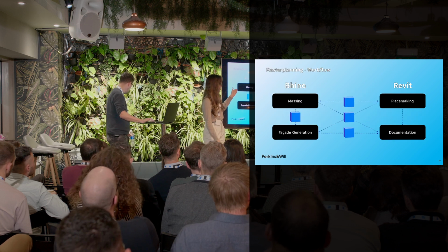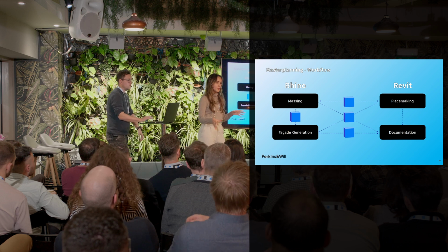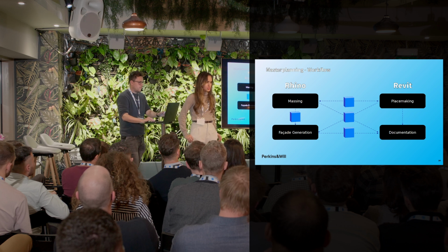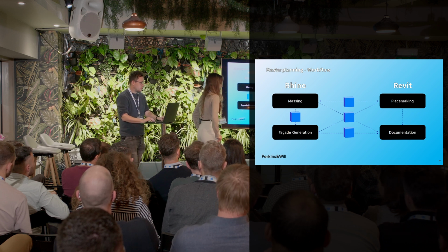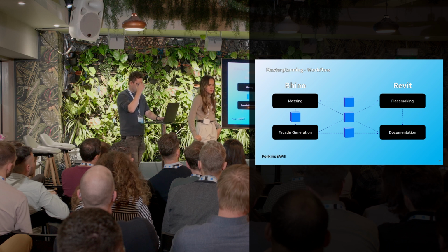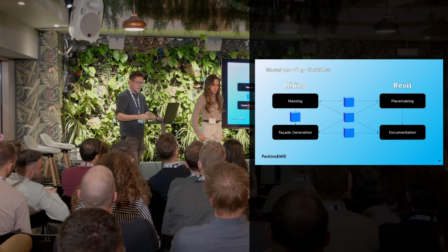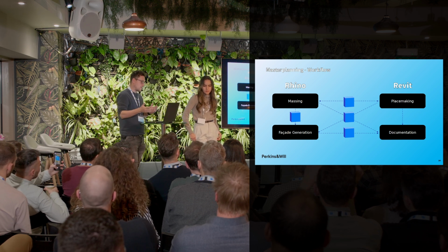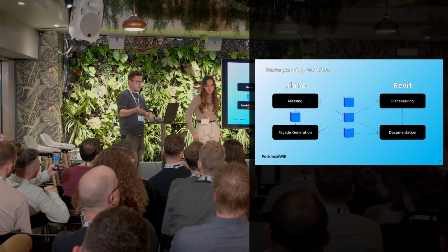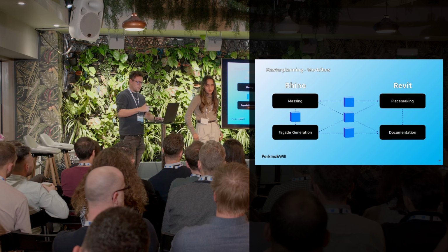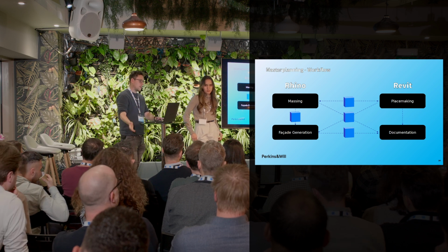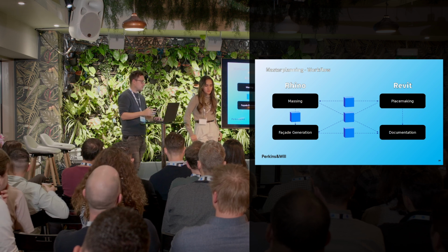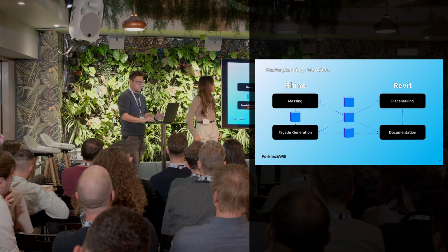This is the workflow. We're going to have massing in Rhino, then send it to Revit and finish the documentation there. And we have like 40 projects using this workflow. Yes, we have a lot of projects using this workflow. For example, if we're doing our massing in Rhino, we'll send it to Revit, and our landscape team maybe edited a park or some trees, and we have to go back to the massing team to update it. Or maybe there are now trees in front of our facade generation, and using the Speckle connector for Rhino or Grasshopper, we have to update and respond to how the landscape is working. We can do this much more easily and live using the Speckle connectors, and then we can document it in Revit.